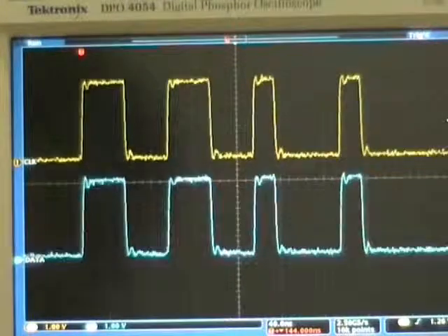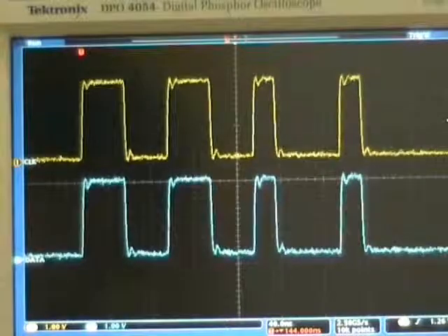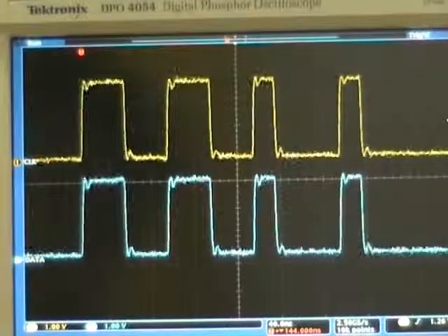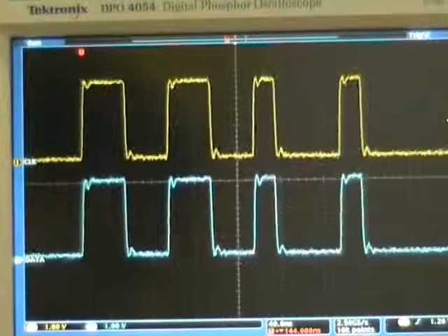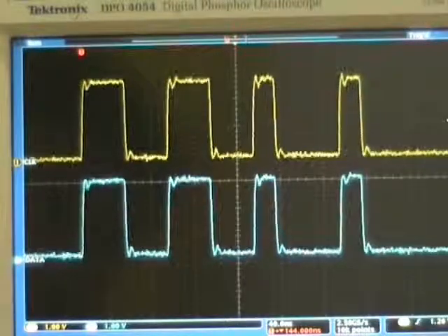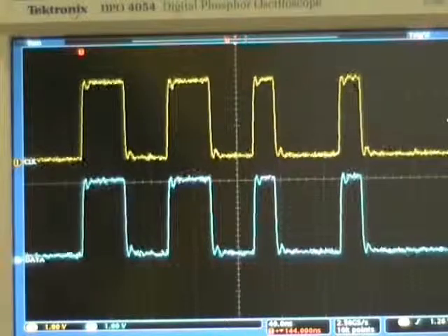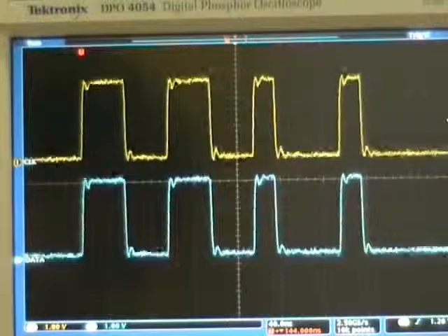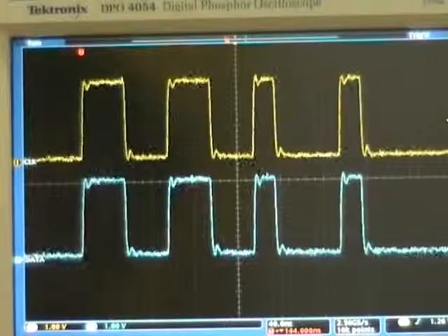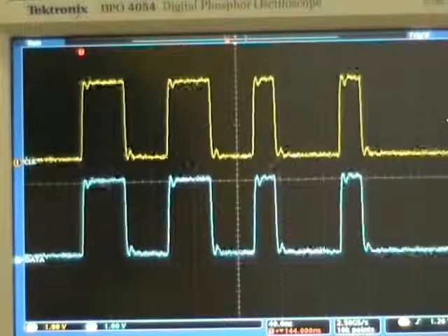Similarly, for the blue curve, we have configured to use the same time sets as the yellow curve, which means time set 1, non-return to 0, and time set 2, return to 0 at 25 nanoseconds. Therefore, the pulse width of the return to 0 portion of the curve is narrower than the pulse width of the non-return to 0 portion of the curve.